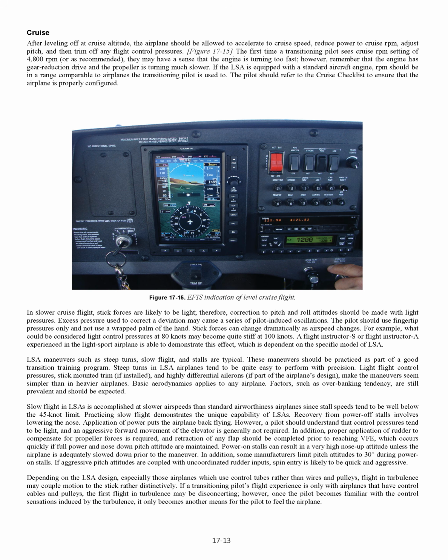The pilot should use fingertip pressures only and not use a wrapped palm of the hand. Stick forces can change dramatically as airspeed changes. For example, what could be considered light control pressures at 80 knots may become quite stiff at 100 knots. A flight instructor-S or flight instructor-A experienced in the light sport airplane is able to demonstrate this effect, which is dependent on the specific model of LSA.